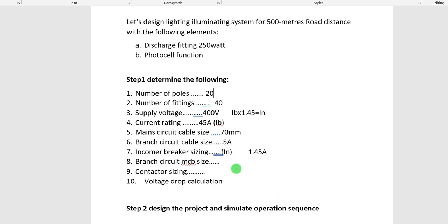Take note, do not increase the size of IN, because in terms of fault, it might not trip on time if you further increase it more than this. Before the regulatory body set aside this, they tested different factors and found out that this one is most suitable. That is why they have chosen this factor for us to augment this.